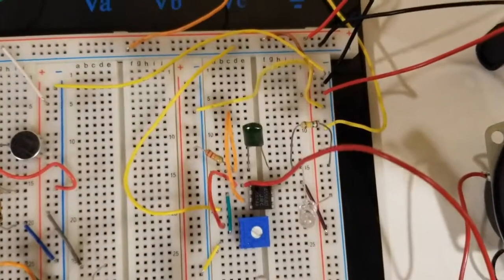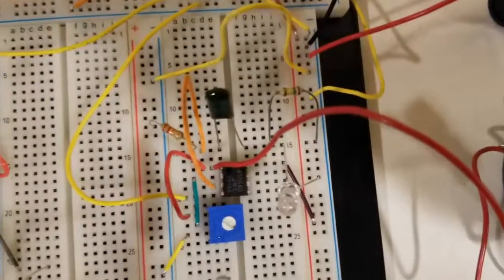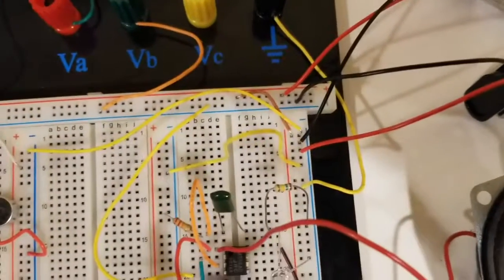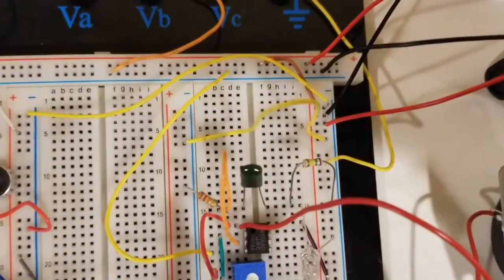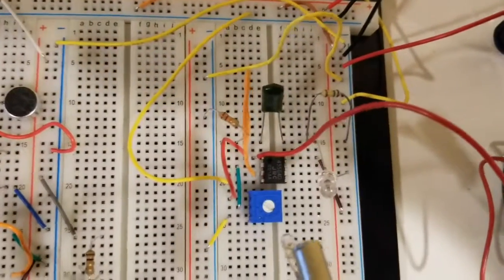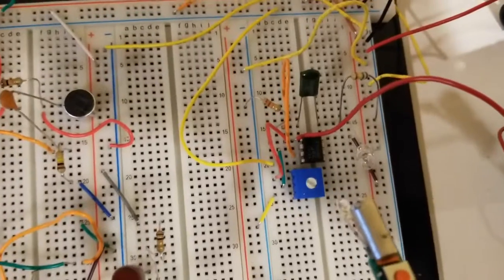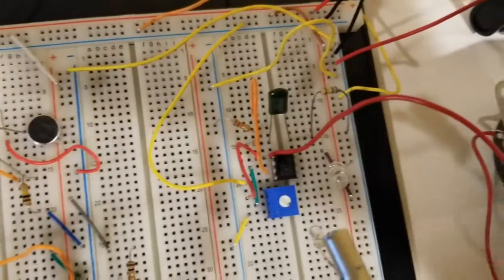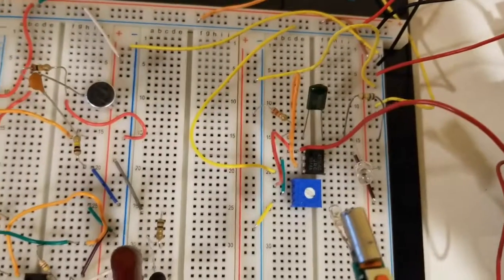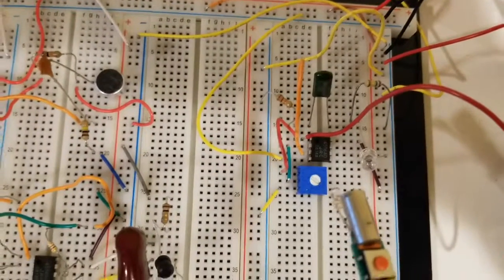For the receiver circuit, we have the photodiode, which is right there, connected into ground as well as to that resistor. Then we have another filter at the top of the op amp to filter out a little more noise. And then we have the op amp itself connected to the potentiometer, which acts as the feedback resistor for this circuit. We had to adjust that a little bit to figure out what kind of volume we could get from it.